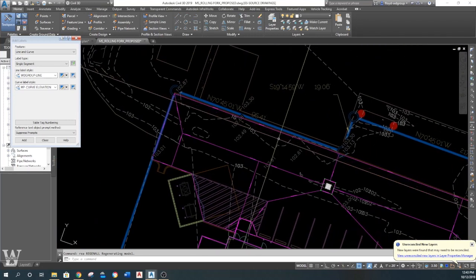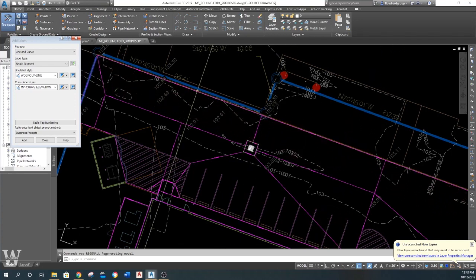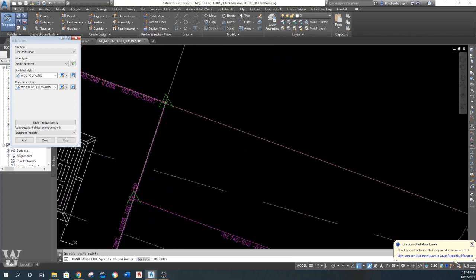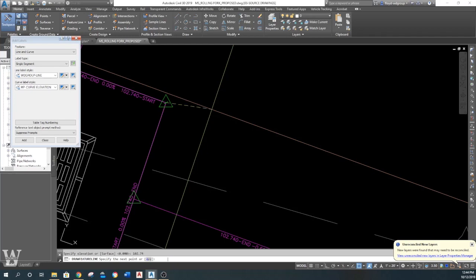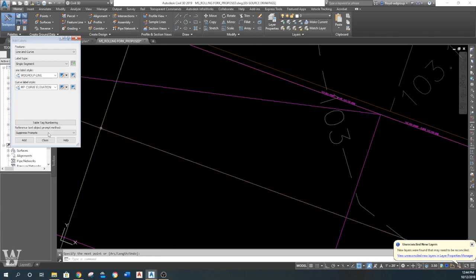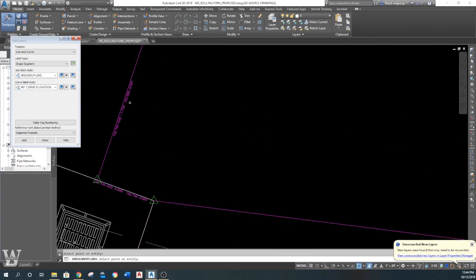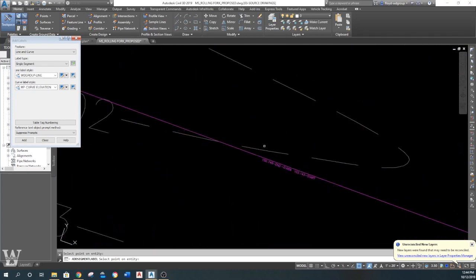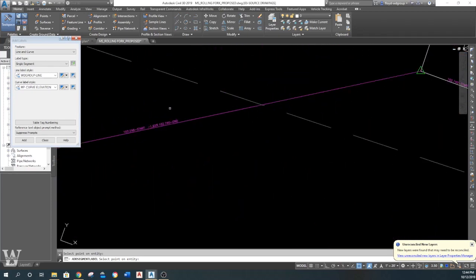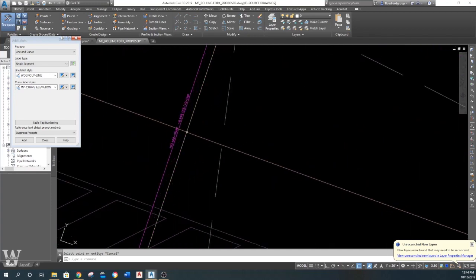So what that tells me is now the water's coming this way, and I need to check it right here also at 102.74 to right here, and the grade on that one is .52%. So I should be okay. If all these grades are greater, I should be okay with everything.